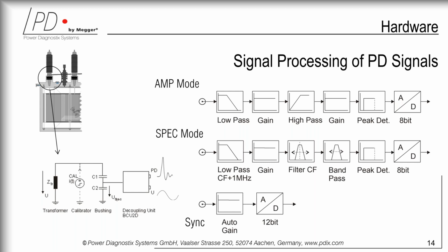So before, and in fact even during the factory acceptance test, the calibrator is used in order to calibrate for a certain level of picocoulomb partial discharge. Usually they look at 100 or 200 picocoulomb, they inject that to the bushing, and then of course they want to read the same amount through the bushing tab, and eventually the instrument should be able to do that. And so, in order to do that, certain calibrators are being sold and used in order to properly do the test.